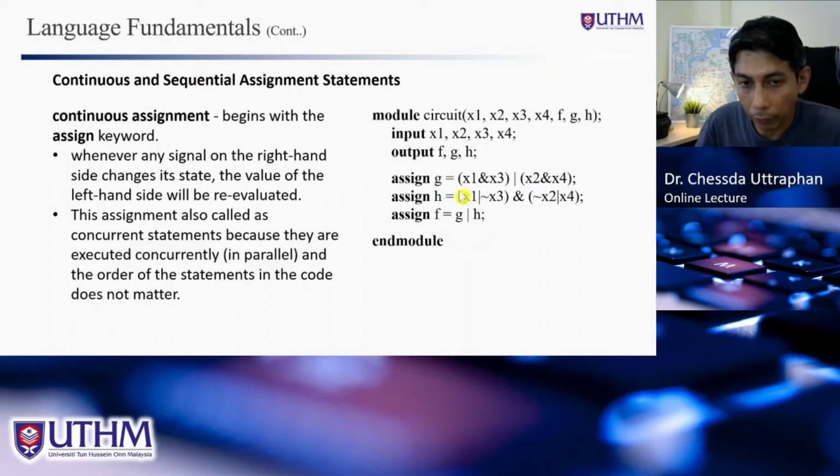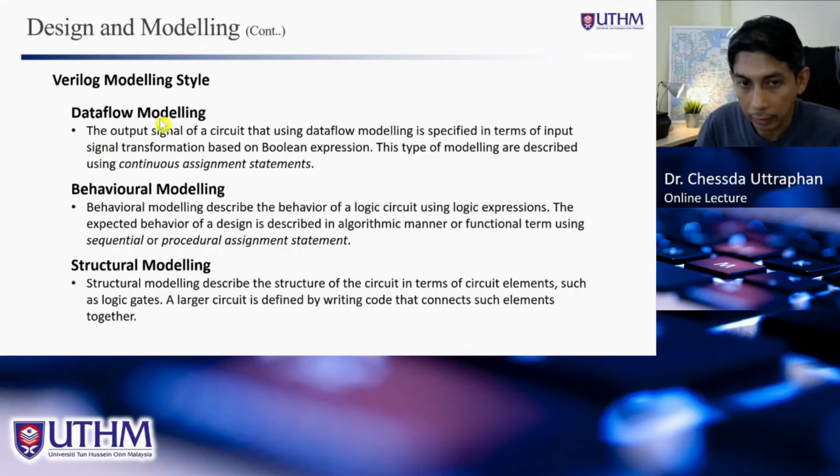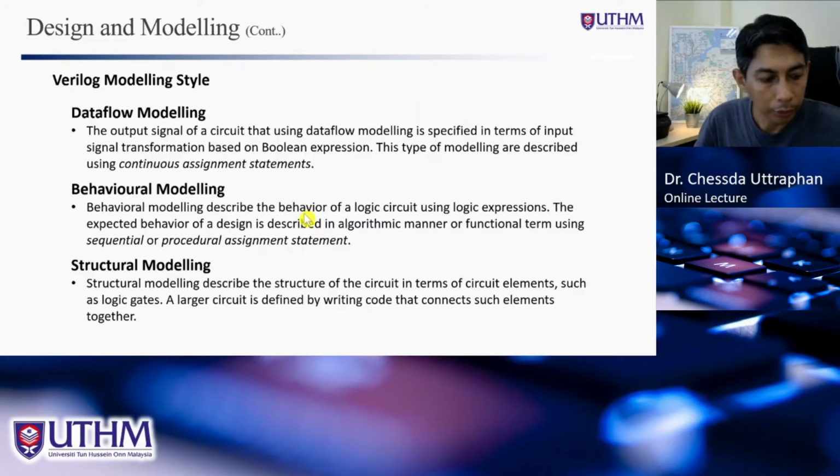And of course, when you use a continuous statement, you will use the Boolean equation. Remember, when you use Boolean expressions and describe your circuit using continuous assignment statements, with the assign keyword, it means that you are designing your circuit using data flow modeling.